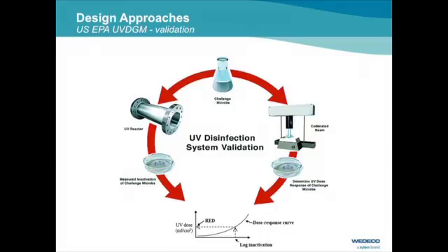And a validation works that way, that you have a water sample and you determine via this collimated beam apparatus how the dose response behavior of these challenge microbes is. So by that you get such a curve, here this curve. And then you use the same challenge microbes, spike them into your reactor under controlled conditions in terms of flow rate, UV transmittance, and so on and so forth.